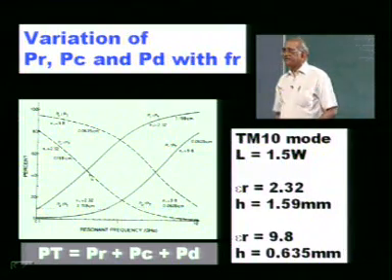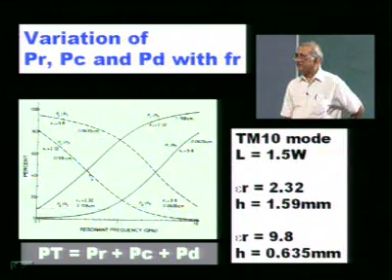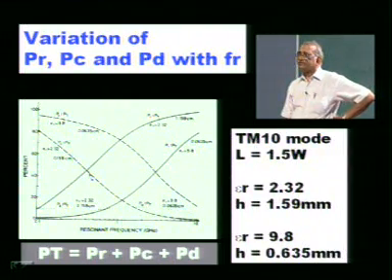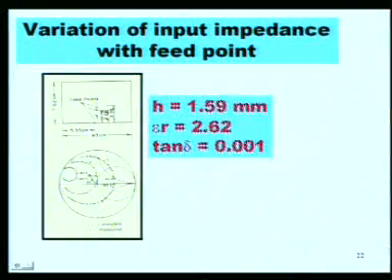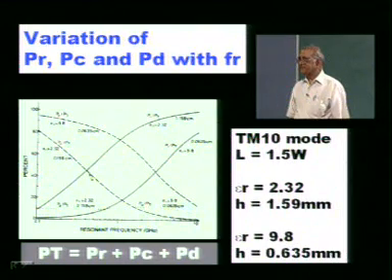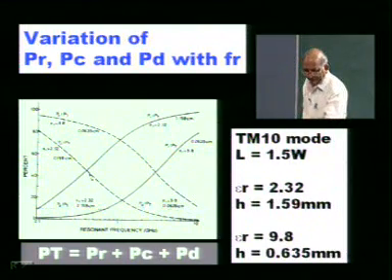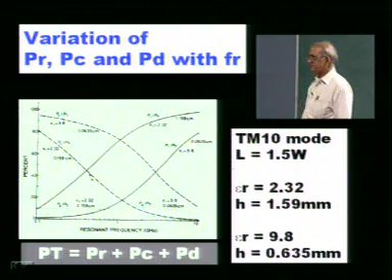So, most of the time when you are using a low loss substrate, and in fact these are specialized types of substrates which we use for microstrip antennas, they are very costly. Something like, as we have said, a loss tangent delta of 0.001. This is a highly costly substrate, and as a result the corresponding loss in the substrate is less. That is why it is shown that compared to the power loss due to the conductor and radiation, this loss is very small, and most of the time we can neglect it.